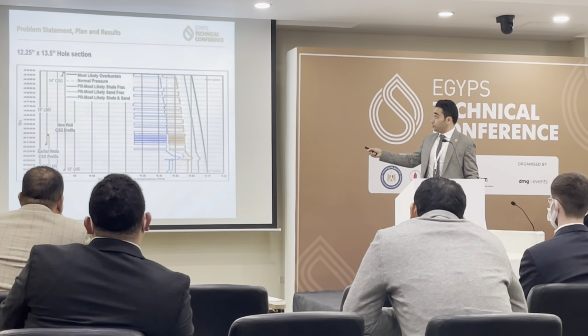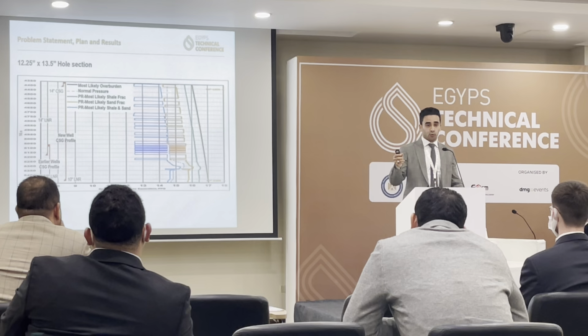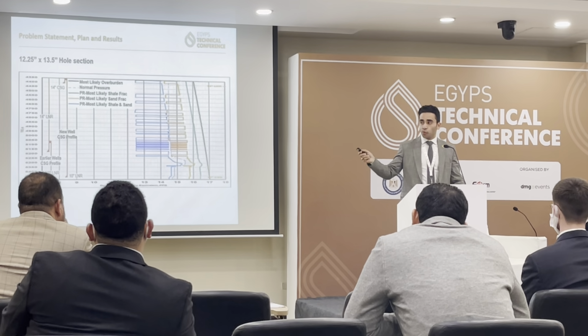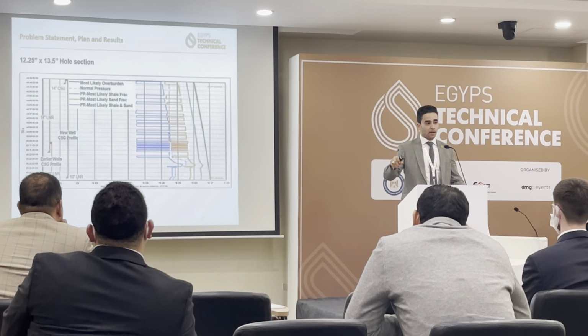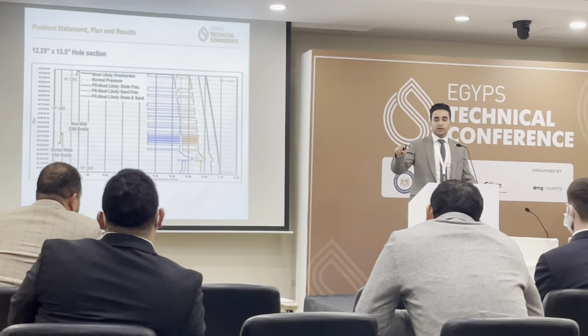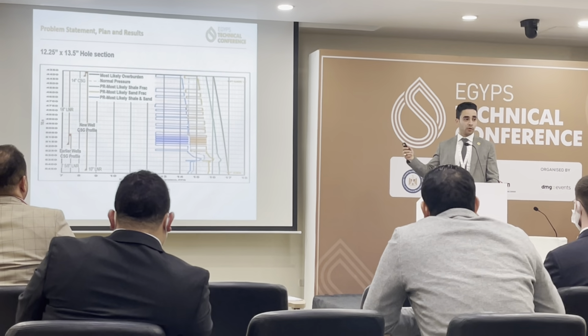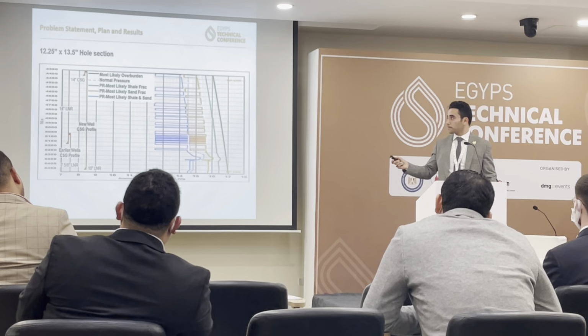After confirming, during this section we had a high level of gas, up to 20%. So we stopped drilling, lowered the downhole pump rate, and continued drilling, adding connections when the gas level came to an acceptable level, 4%, 5%.